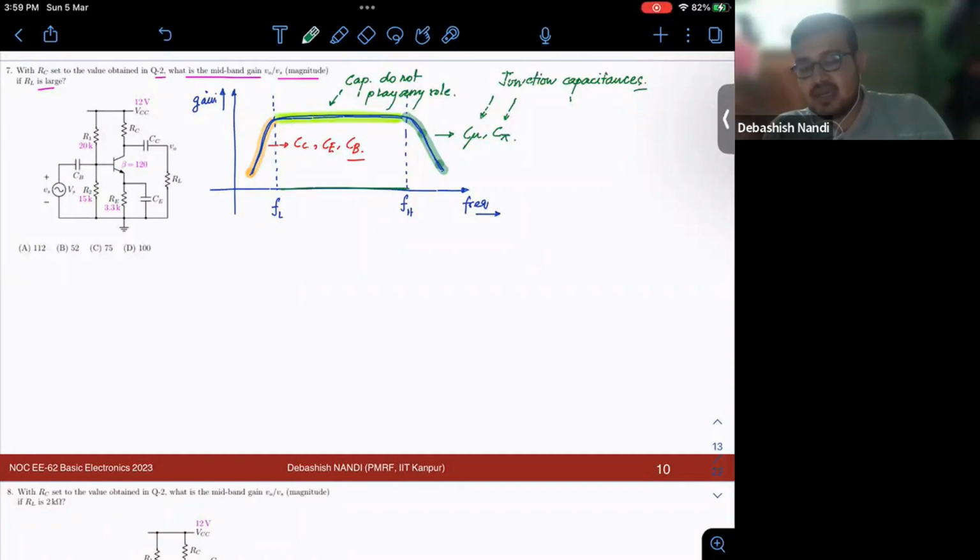So this means that if you sweep your frequency, there is no element in your circuit which is responding with respect to frequency. Now in your circuit you have controlled sources, independent sources, and resistances. These are all frequency independent elements, right? Only if you have capacitances or inductances do you have a frequency varying response. So as you have rightly said, as it is constant, no capacitive action is effectively played in this region, right?